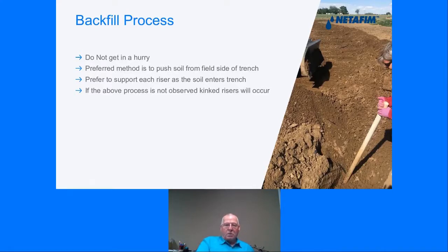In the backfill process, the real key here is don't get in a hurry. The preferred method is to push soil from the field side and push it back into the trench. We push it in slow. As you can see here in the picture, we're supporting that riser right there. We prefer to support each one of them as the soil enters the trench.